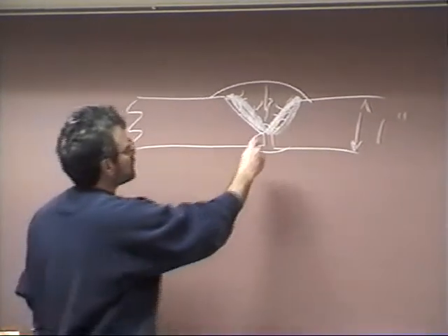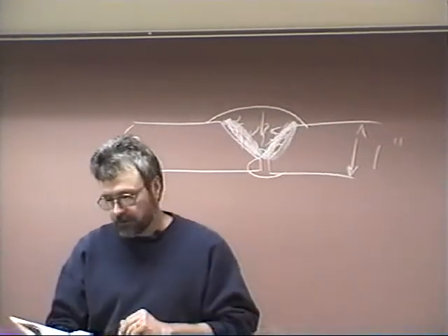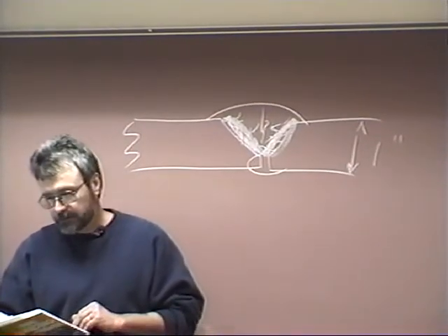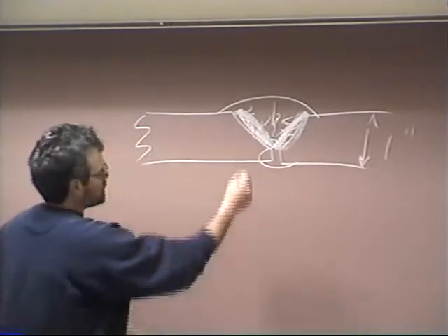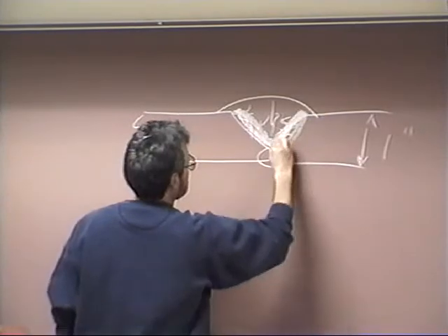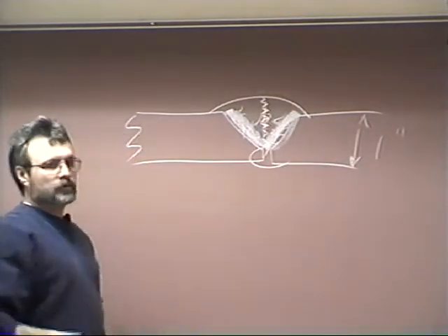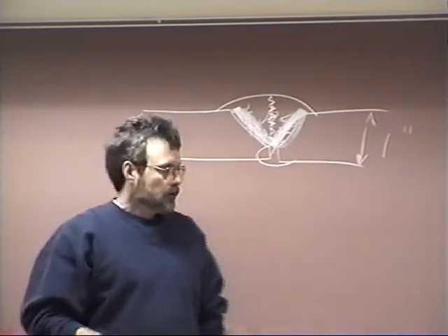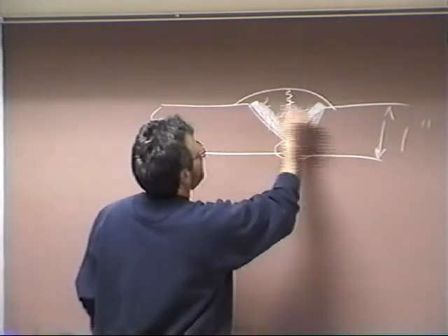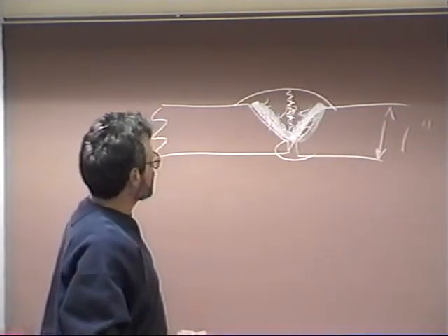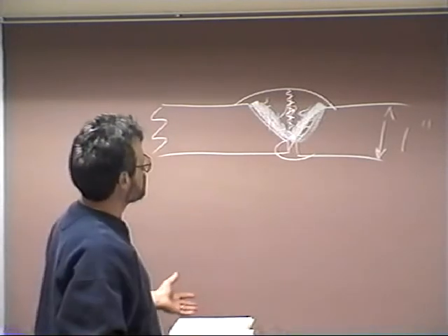Well, when that happens, the stresses are building up out in here. And if you look at figure 13.2 in your textbook, it's on page 210. What happens when you have this non-uniform cooling, it's going to solidify here, and it puts stresses here, and it can crack right down the center, which would be a throat crack. So you want to try to make sure you've got uniform cooling on this thing. And if you can't, then what are you going to do to relieve it?